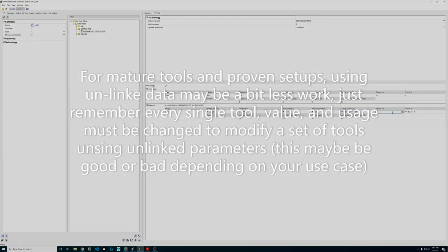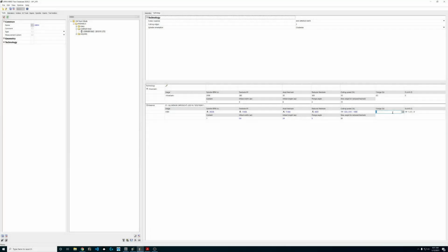And then on the feed rate side, it wants to see the feed rate on the 12 millimeter tool at 0.336. So again, let's divide 336 by 144, and we're going to get 2.33. So these are some pretty robust parameters. So you're going, oh my God, 26 meters a minute at 26,000 RPM. There's no way my machine can handle that.